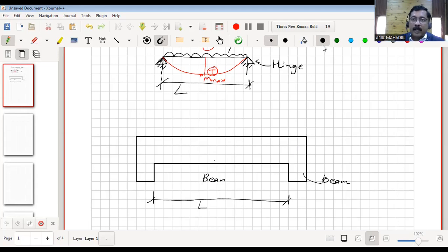So on site, how are the structural drawings prepared? We design the steel at the bottom for Mmax and we will provide such kind of reinforcement. So this is the reinforcement at the bottom. And to optimize the steel quantity, we generally curtail the bars also. So this will be a kind of curtailment. We are providing maximum steel at the bottom. So this total steel, this bar plus the curtail bar, is our total AST for this Mmax.